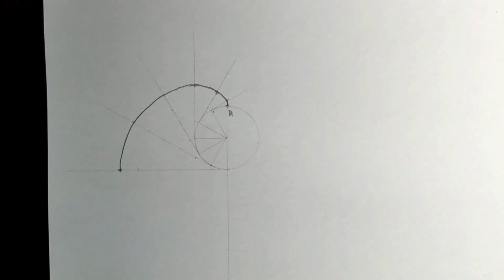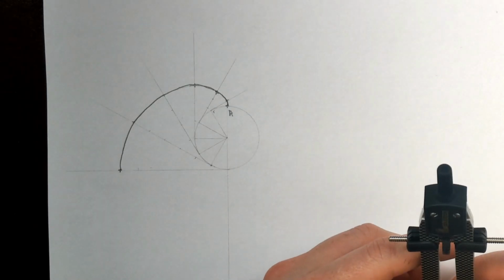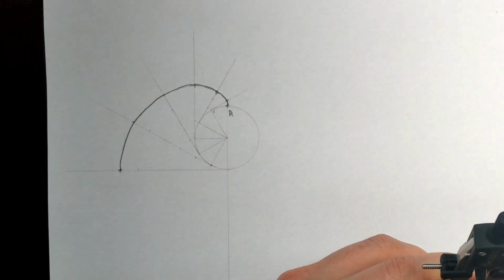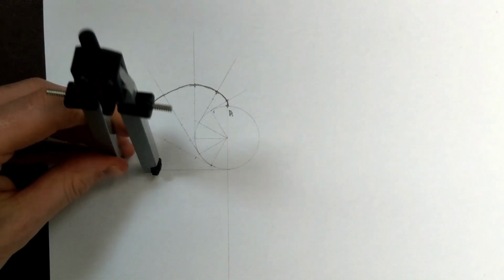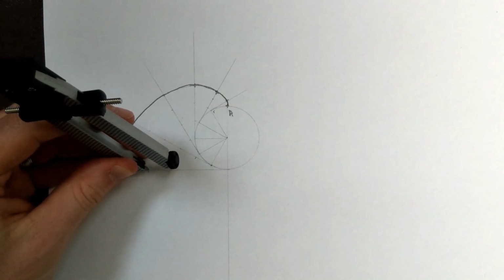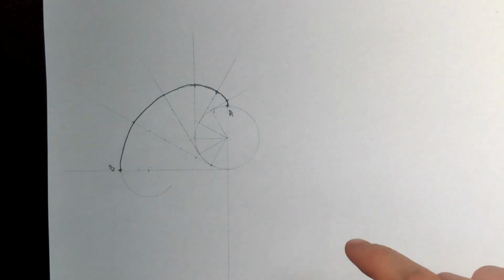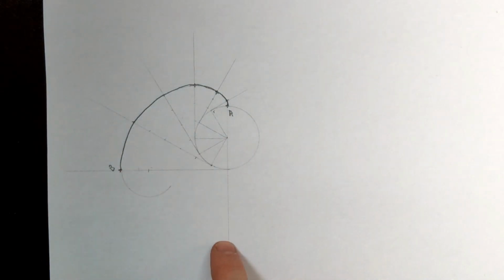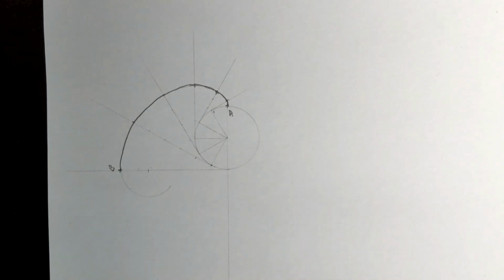Now, as for the rest of it, we have a radius 15 arc here, so I'm just going to pop 15 on my compass. Okay, so that's point B found. So I'm just going to swing my 15 in there and draw an arc. Right now, I'm not going to darken it in yet, I'm just going to draw it lightly for the moment, because I have a straight line that goes down here as well, that I want to get to.